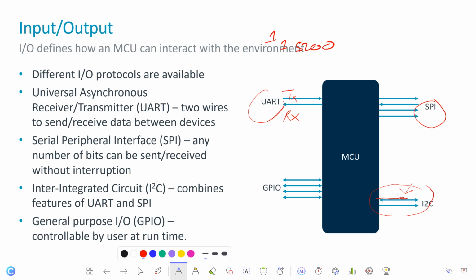So the I2C works like the UART in the sense that the data is sent in packets, but in a synchronized fashion like the SPI. Two wires are used between a master and the slave, though the master can support multiple slaves. Serial data is used for data exchange, and serial clock is used to carry the clock signal. The packets are delimited by the start and stop condition, and the first 7 to 10 bits are used to identify the slave address.